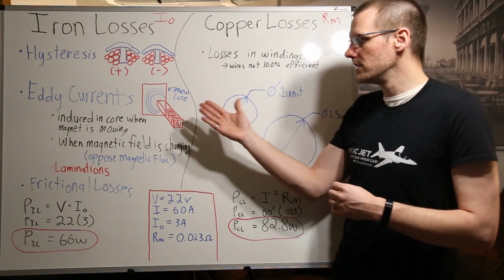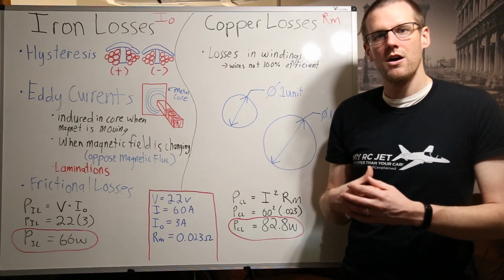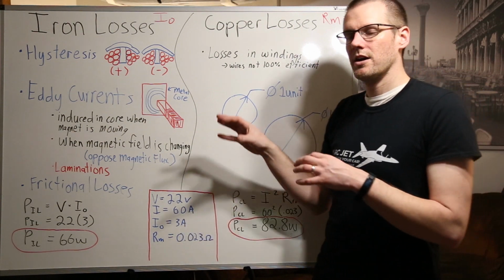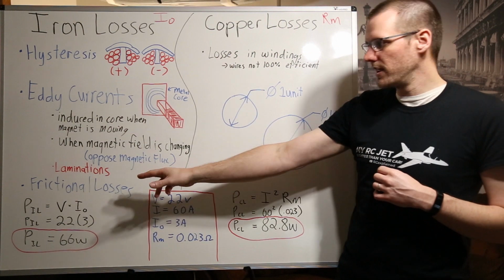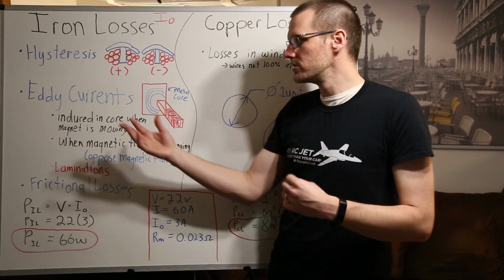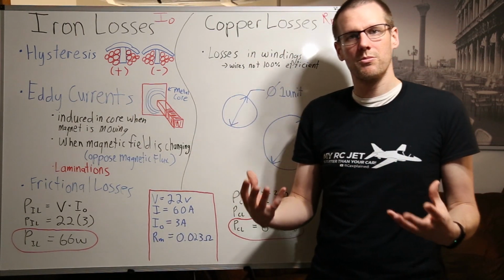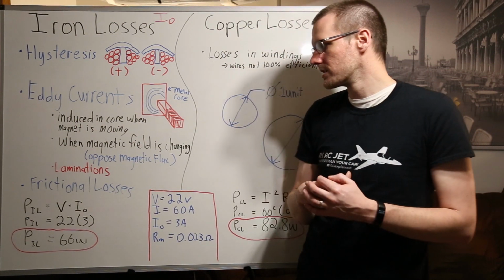If you decrease the laminations even further, you can also reduce the eddy currents further, although you do get into other trouble when you go through that sort of idea. But this is definitely one way that motor manufacturers are producing laminations to reduce the amount of eddy currents that you see within a brushless motor. Now you understand why we use these laminations in our motors.